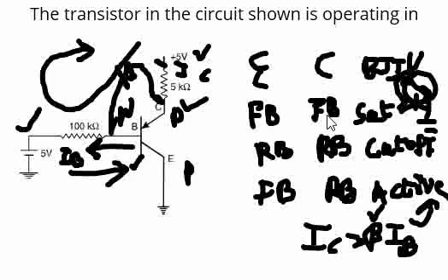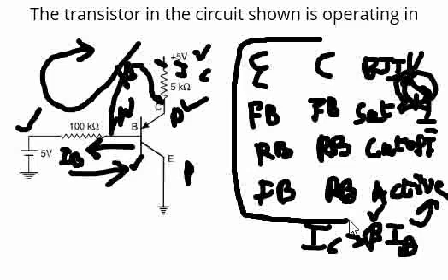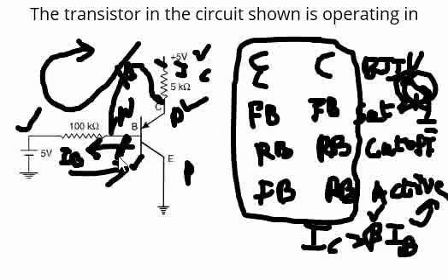So simply by looking at this table, if this particular circuit has to be in operating condition, the simplest thing that we can say is here we have to reduce the voltage. So for this to be operational, if we want to make the collector junction forward biased, this voltage should be less than this voltage, so that the junction turns on.